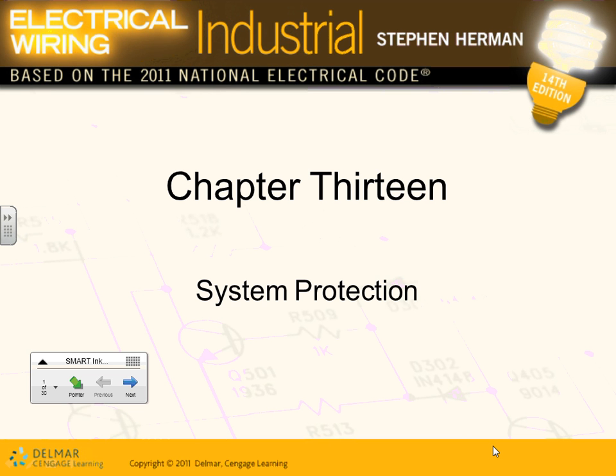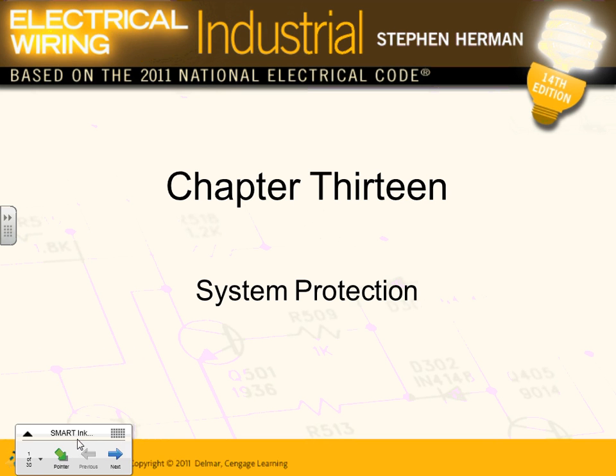So this chapter talks about system protection. When it comes to power system protection, guys, there are multiple protections that you can provide for the system. One of them is the overcurrent protection device. If the current goes above a predetermined value, you need the circuit breakers to trip before you burn your equipment. If you have a short circuit, you need the circuit breaker to trip before you burn equipment. That's what we call an overcurrent protection device.